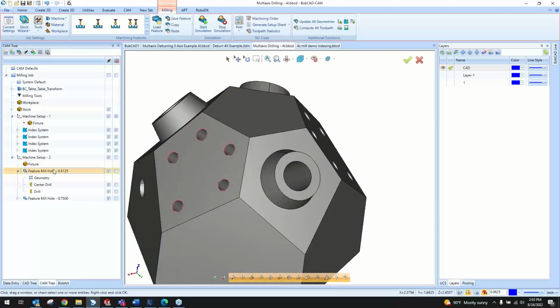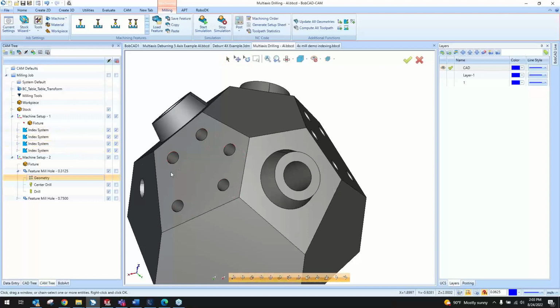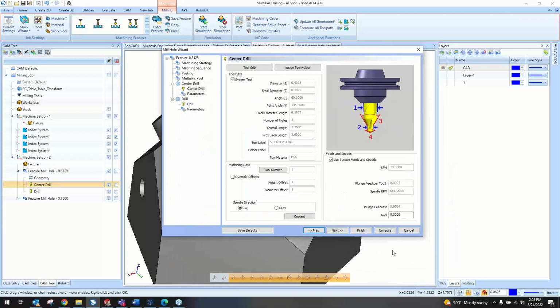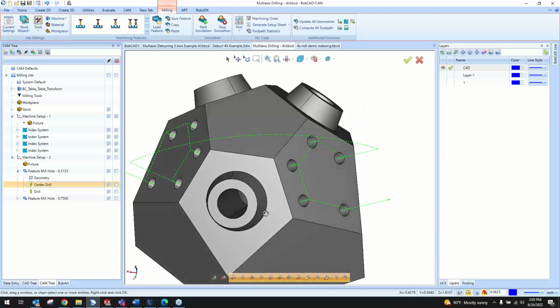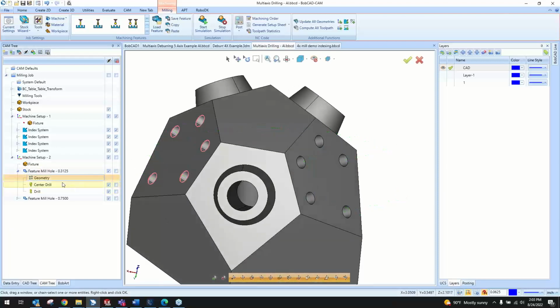Makes things a lot easier so that you just have that drop-down option in the geometry selection of multi-axis drill, so you don't have to index on each one and you need a flat surface every time. You can just go into multi-axis drill here. Same kinds of settings here. What's that toolpath? Oh, right, okay.